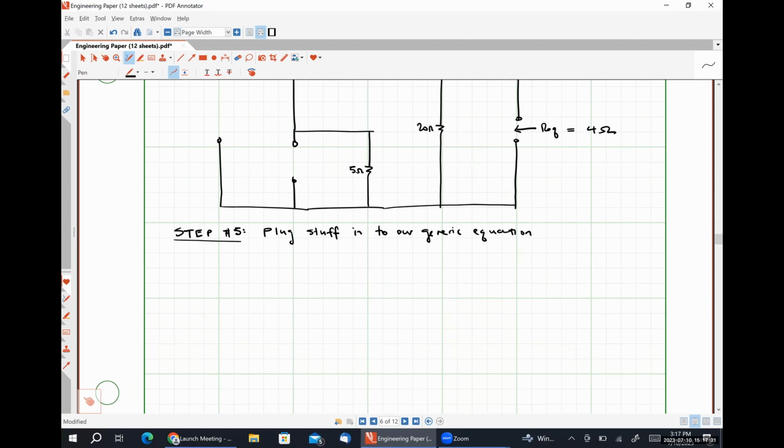So to remind you, our generic equation is as follows. Y total is y at 0 minus for t less than 0 minus, and it will be y at 0 plus minus y at infinity, e to the negative t over tau, plus y at infinity for t greater than or equal to 0 plus.